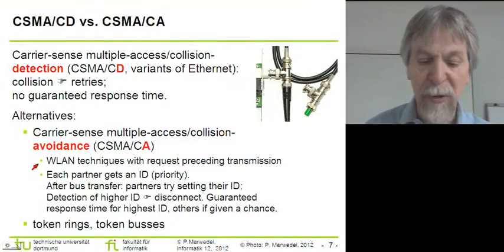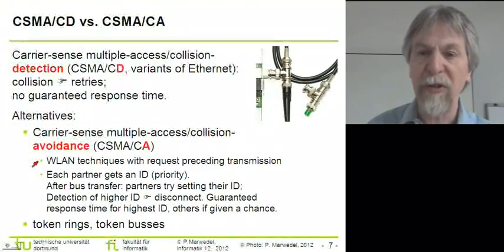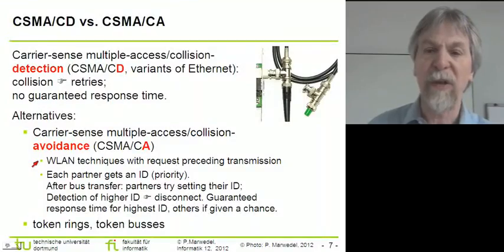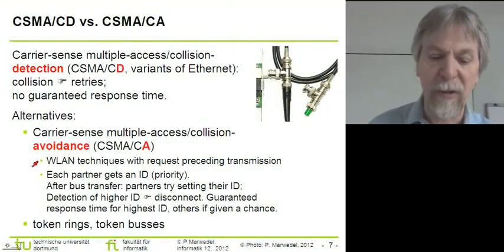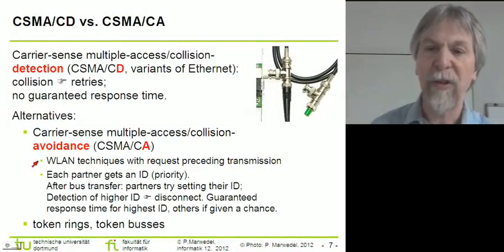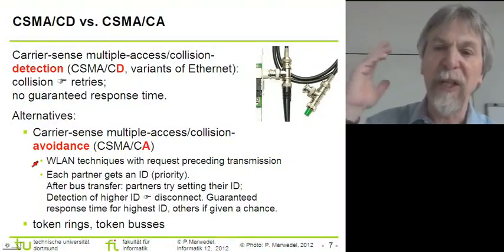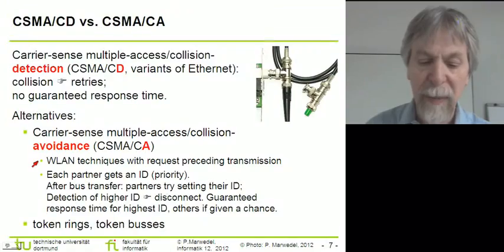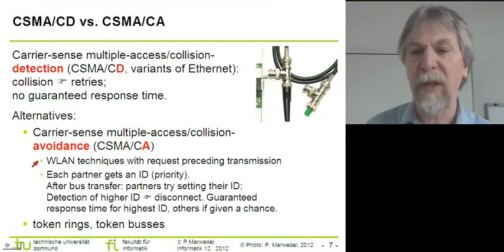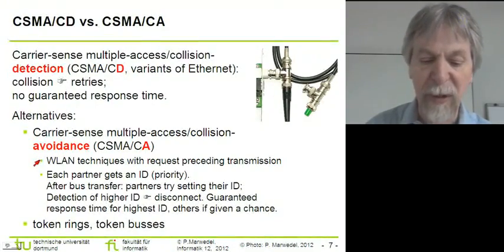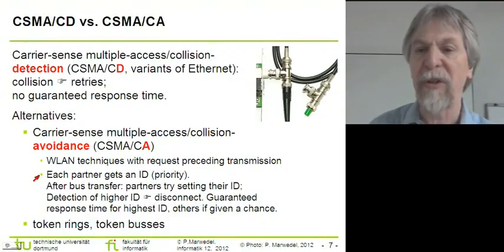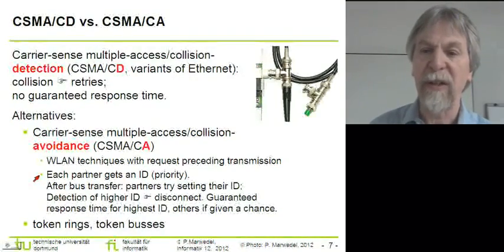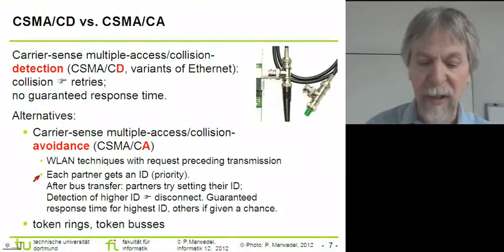There, before we do the actual transmission, we check which of the communication partners would like to communicate, so the communication partners can kind of raise their hands and tell the system, oh, I'd like to communicate. And then the highest priority among all those partners will be considered, and that will be the one that can actually then transmit the message.